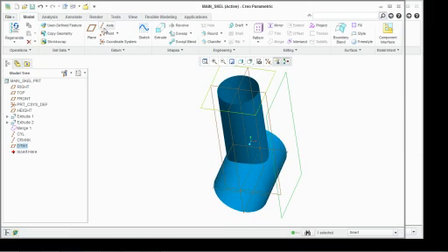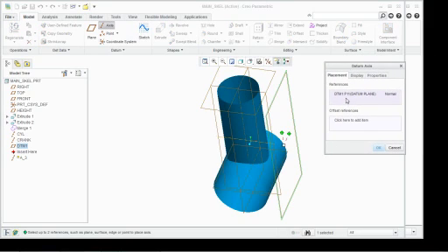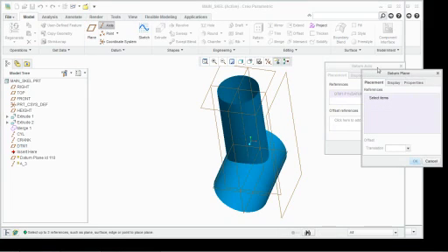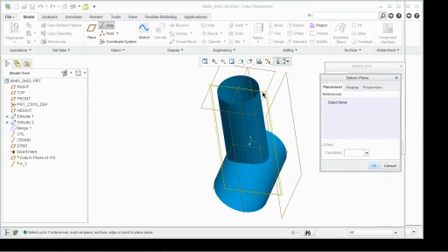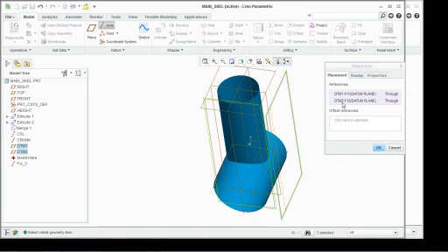And then I'm going to create an axis. With the datum axis tool selected, notice it did select datum plane 1 already. I'm going to select a plane tool on top of that. I'm going to pick this front plane and offset that 20 in that direction. Or no, this is the one that's supposed to be 10 here. When I click OK, it brings datum plane 1 and datum plane 2 both into the axis.